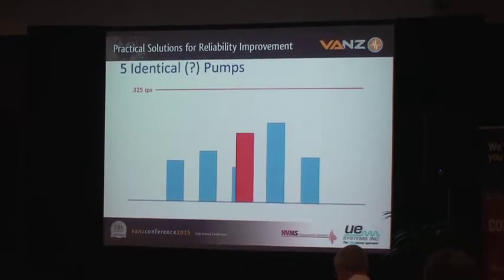and I took data on the number 3 machine, and that's the relative amplitude that I found. I mean, the thing just really, really sounded nasty. A couple things I would like you to notice. The amplitude on that number 3 pump increased by pretty close to a factor of 2. And recognizing the fact that I parked in the same spot every single day, the fact that I hadn't heard that noise Wednesday night when I left the plant, and Thursday morning when I came into the plant, I heard this really, really nasty noise, and I went in there and I took that data, I kind of considered that factor of 2 increase was probably something pretty significant going on.